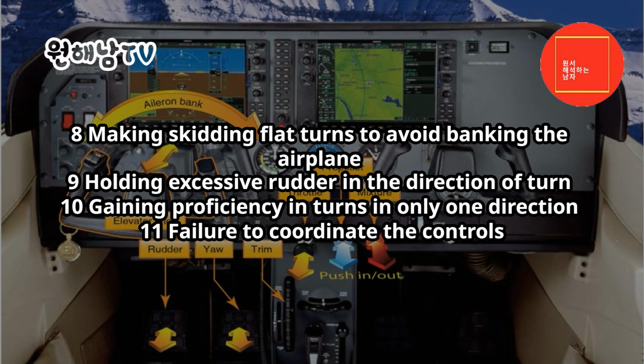8. Making skidding flat turns to avoid banking the airplane. 9. Holding excessive rudder in the direction of turn. 10. Gaining proficiency in turns in only one direction. 11. Failure to coordinate the controls.